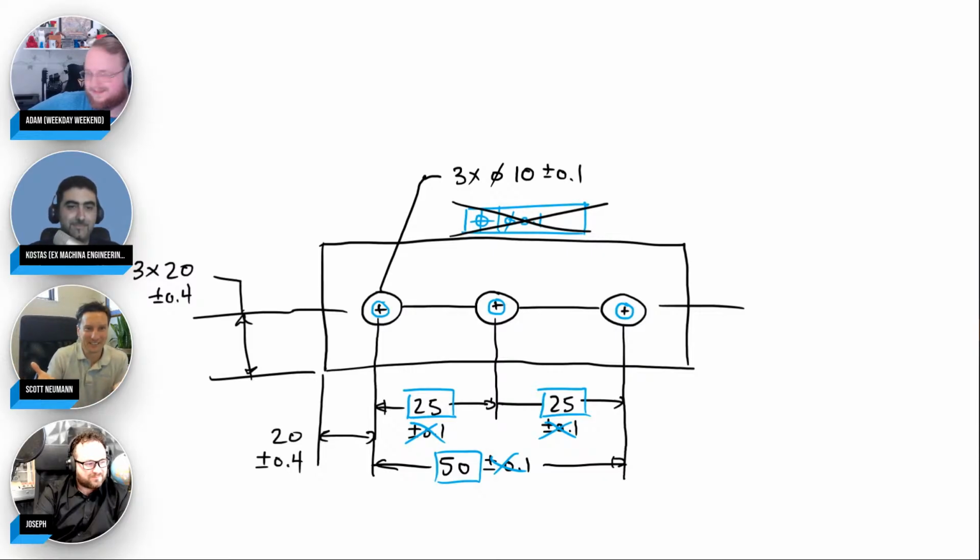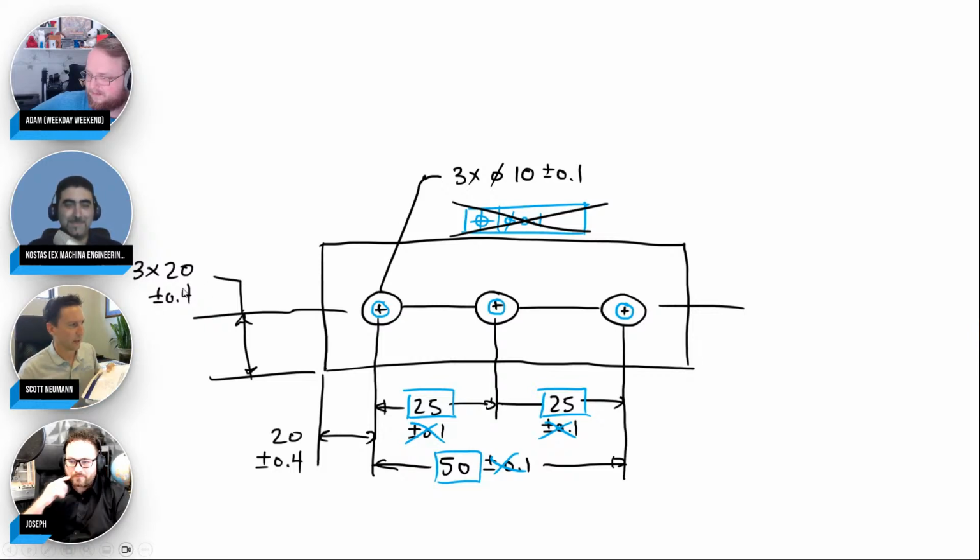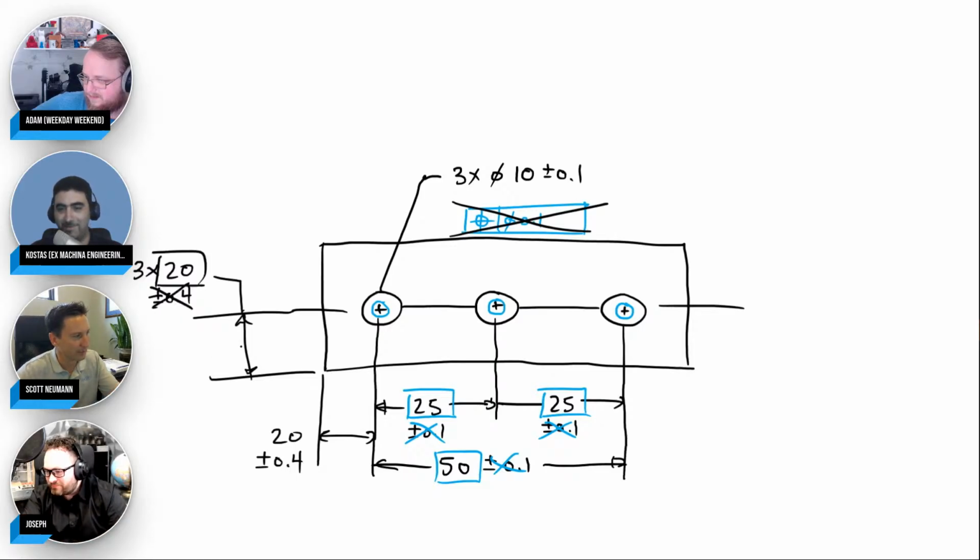Nobody knows the answer to this. I perceive it as that's all we got. Like, this is my assumption. So you go consult the standard, like, what does the dimensioning and tolerancing standard say about that? And the standard says, you're on your own, buddy. You're using a plus minus system that's unstandardizable. So that's why we don't do this anymore. We don't tolerance the dimensions. We make it all basic. Make it all true.